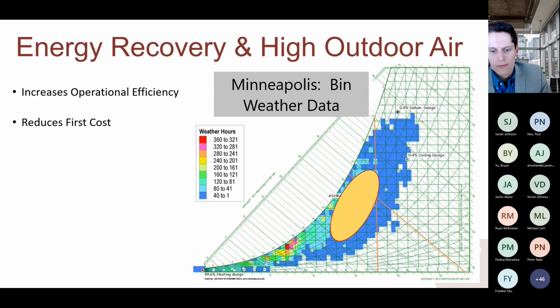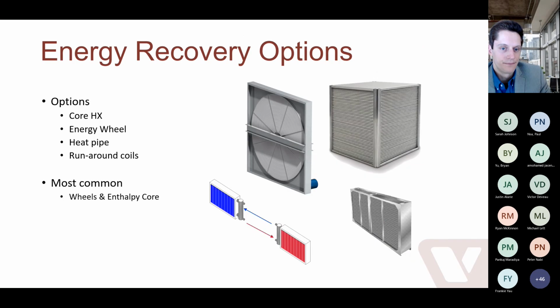It also can reduce first cost. If we add energy recovery, that means that we can sometimes reduce the size of our heating and cooling equipment. It makes our unit more energy efficient and can meet that ASHRAE standard 90.1, which requires energy recovery in certain cases.